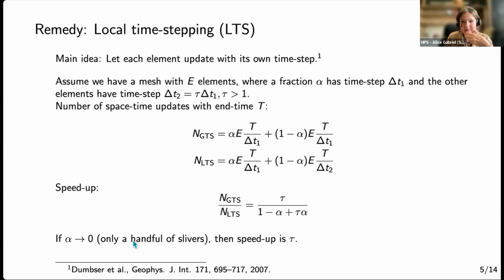There's a little bit of information here basically explaining how much of a speed up you can expect from using this. And we are defining a sweet spot: not really each element updating with its own time step, but clusters of elements grouped together that are updating with certain smaller and larger time steps.